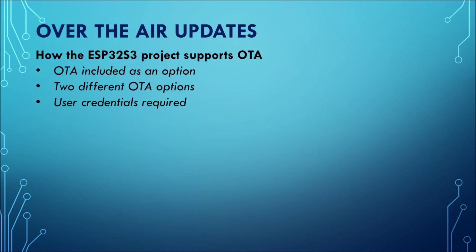In this project, OTA is not included by default. It's an option in the config.h file. And there are two different options available to do OTA, and in order to use the OTA you have to know what the user credentials are, otherwise you will not be able to sign in.